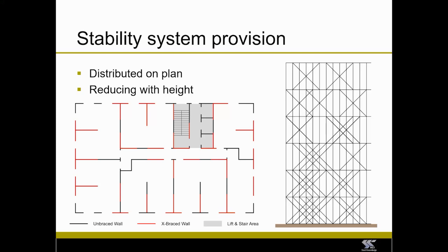This shows various forms of X bracing where we've got overlapping X bracing, and individual X bracing where it's not overlapping, and in this case, offset from each other. You can have the X bracing stacked one storey to the other. Whichever approach is used in a particular structure, you need to make sure that the loads are properly transferred, and you design the members below and above each storey for the forces that are transferred from the X bracing.